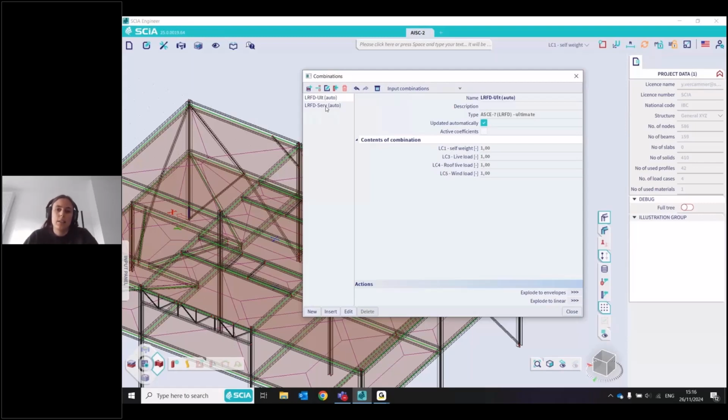And on the other side, in the ASD, allowable stress design method, we will just consider the loads as is, no safety factor applied on top of them, but we will greatly limit the stress allowed in the structure. So there will be just a big coefficient at the end on the stress in the structure. So we will be much lower than what we allow in LRFD. I think today LRFD is also for America the most applied method for steel design, and this is why it is the default choice.